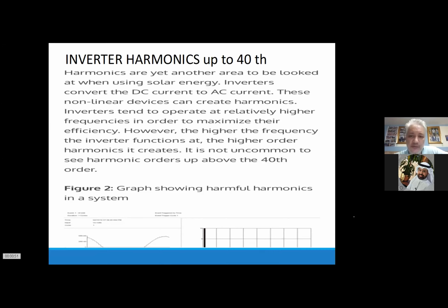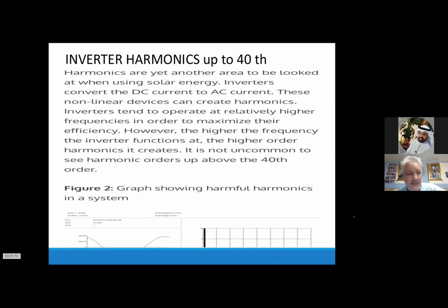After they fixed that, it went below 1%, and the magnitude is between the third and 40th order. So it's actually quite high. Why? Because different inverter manufacturers have between 10 and 25 kilohertz as an MPPT sample rate. So that means we are actually in high frequency noise, and you can actually measure that.